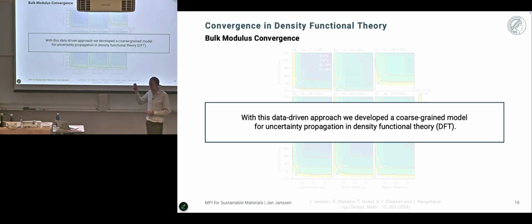Yes, I think we picked the bulk modulus here as an example because we have the volume dependence, and we see that it has an effect. I think just the energy is dangerous because at different volumes, or with different cells, strained cells, cells with defects, cells without defects, I would still do the convergence. But we hope that there's some general understanding that we can discover with this kind of method, and then be able to automate this process.